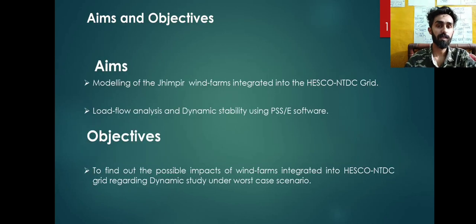As far as the aims are concerned, they are the modeling of the Jhimpir wind farms integrated into the HESCO-NTDC grid, and load flow analysis and dynamic stability using PSSE software. The objective of this project was to find out the possible impacts of wind farms integrated into the HESCO-NTDC grid regarding dynamic study under the worst case scenarios.